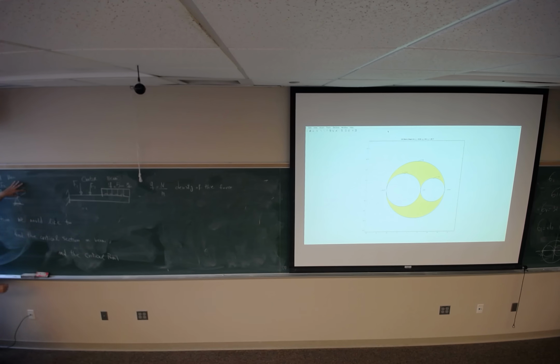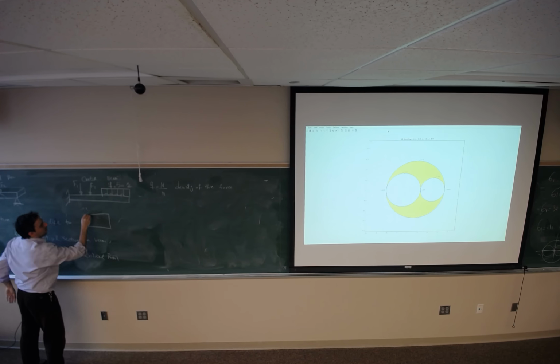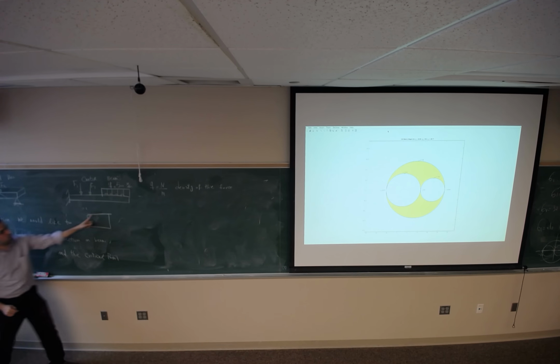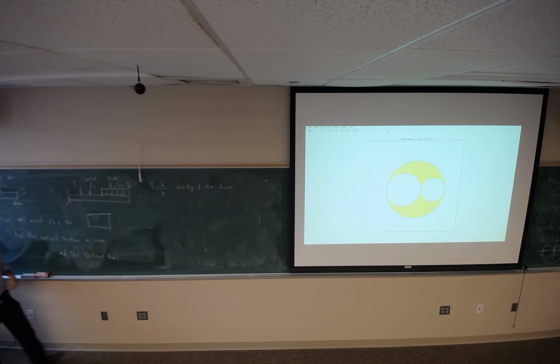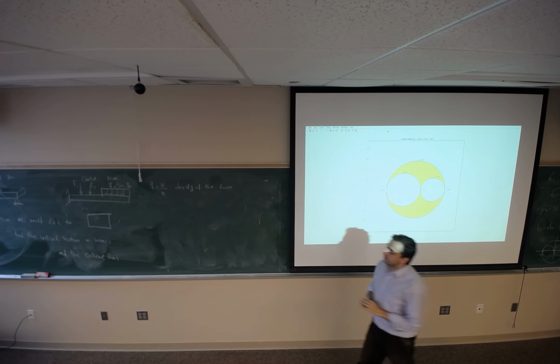If the cross section is this rectangular, I would like to know at this critical section which point of this cross section is gonna see the largest amount of the load, and the failure is gonna occur at that point.